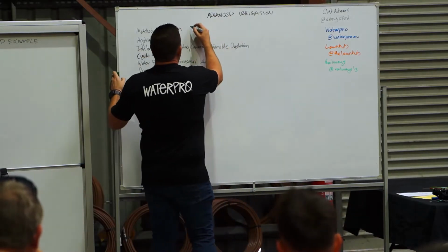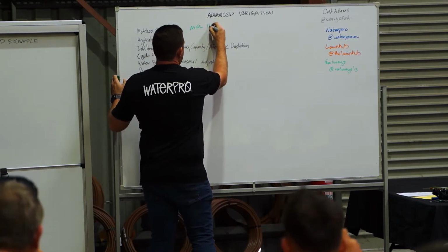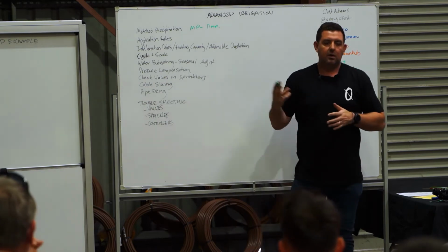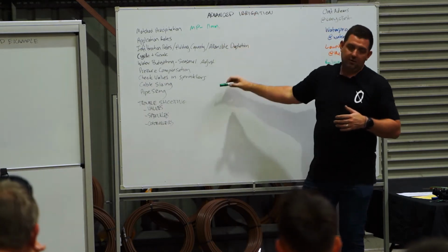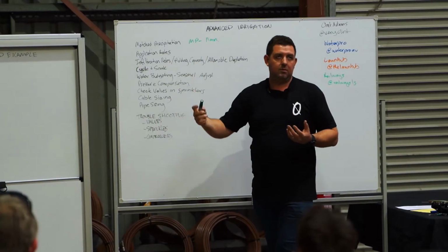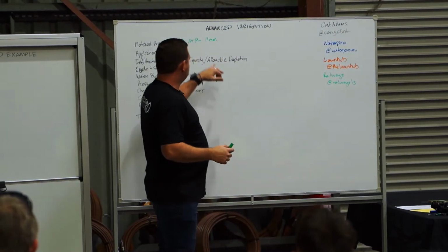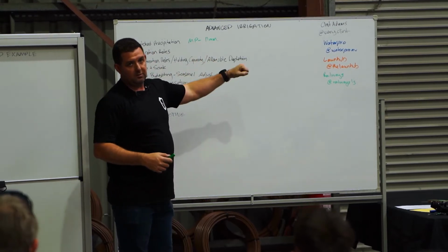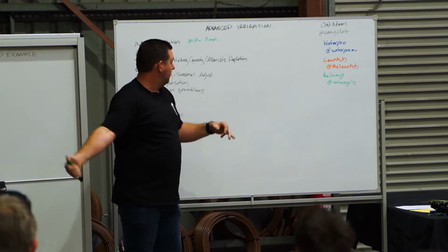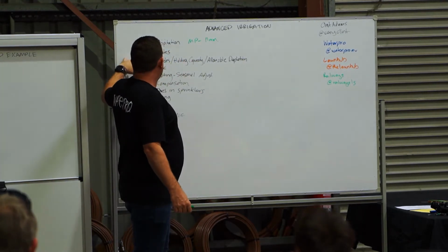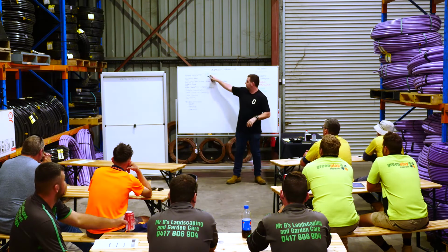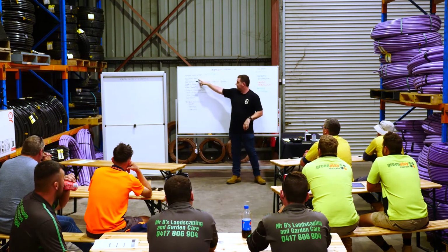So this information is quite important and quite relevant when we're working further down into the scheduling of the irrigation programming, because you need to understand what the sprinklers are delivering to enable you to work out how long you want to run them for and that kind of thing. Now, the application rates jump straight from the precipitation rates. That should have probably been written there. That's the application rate there.